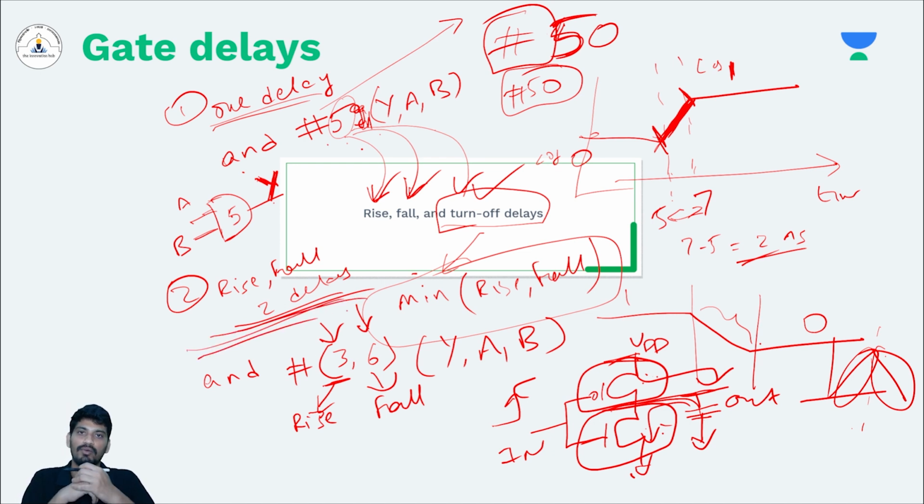You can model your Verilog logic gates with different rise and fall delays, similar to the real world condition. In the real world also the paths are different, and maybe because of process variations, if you don't design the inverter properly, the rise time and fall time will be different. So to emulate that functionality, you can use different values of rise and fall delays.